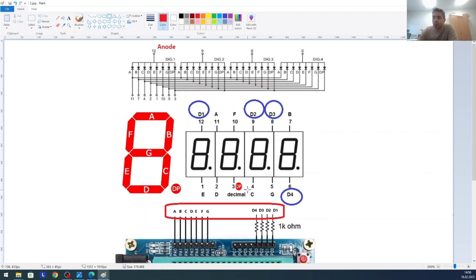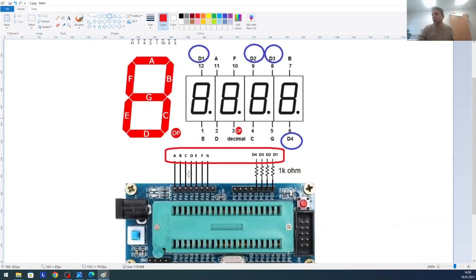Let's remember that when we are configuring in CodeVisionAVR, we have to configure these pins, 4 of them, and not the other 4 that are not used. Pins port C0 through 3 need to be output. The others you should not put as output, because in general the pins that are not used are better to be input, not output, so that by accident you don't connect it to the ground or something else, some big current goes, and the microcontroller will burn because of that.